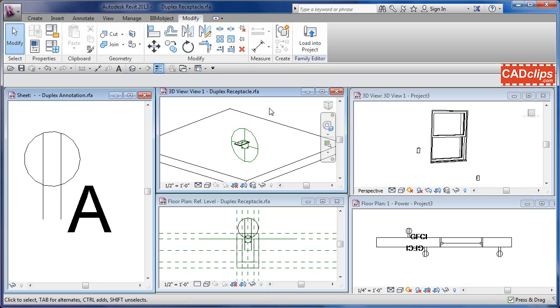It's very important when you create a new family that you use the right template file to start. In the surface-based template file that this family uses, it comes with this object. I really encourage people not to create your own components in electrical in Revit. Take one that's like yours and modify it. That's why this lesson is so important: with this series of videos, you don't really need to learn how to create one of these from the ground up. You just need to know how to go in and take what's out of the box and change it to make it look like what you want.